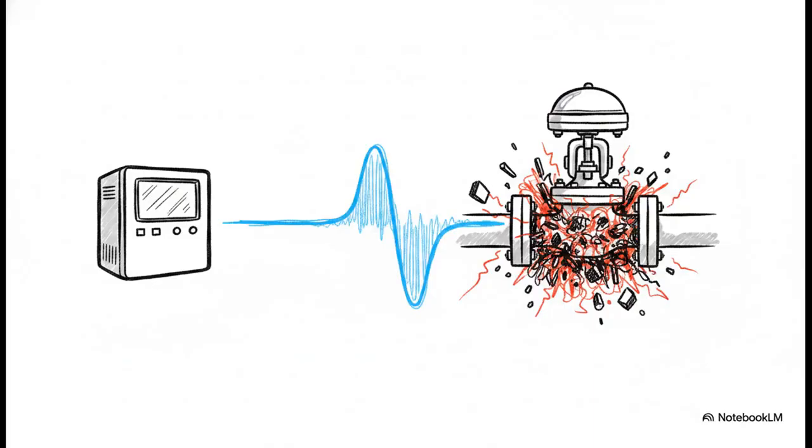But wait, I have a massive real-world warning for you as you're staring at your screens and data trends. Please never assume that the electronic OP percent equals the actual physical valve percent open. Why? Well, because a sticky valve, a miscalibrated positioner, or even reversed action can completely alter reality out in the field. Think about it. Your controller's electronic signal has absolutely zero physical strength on its own, right? It relies entirely on an actuator.